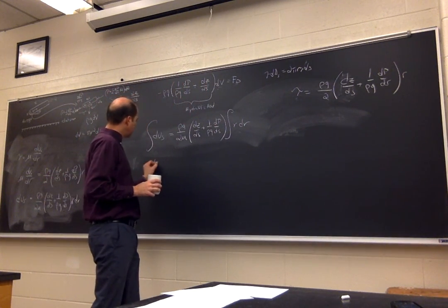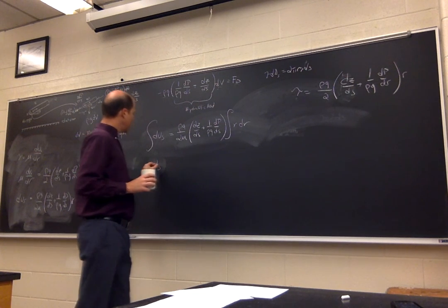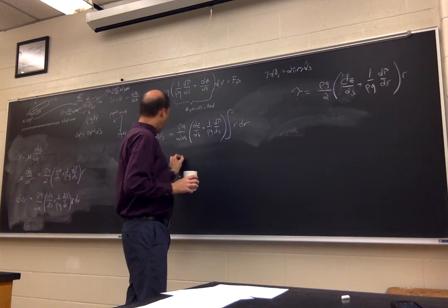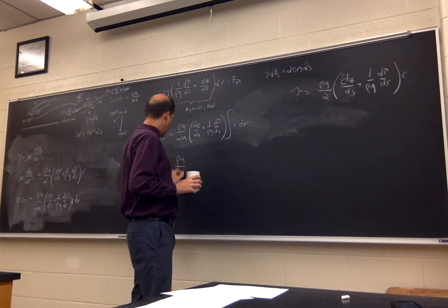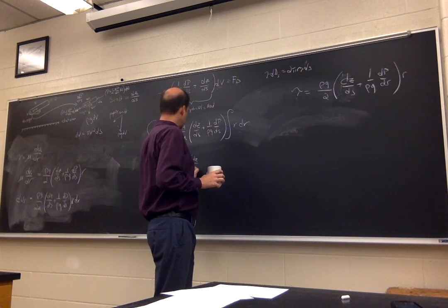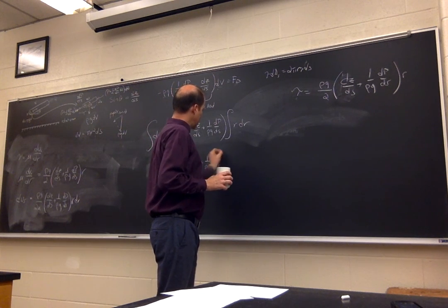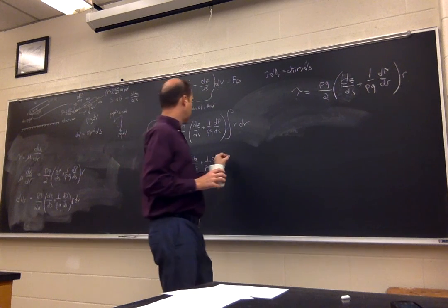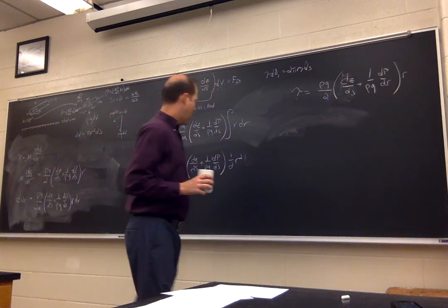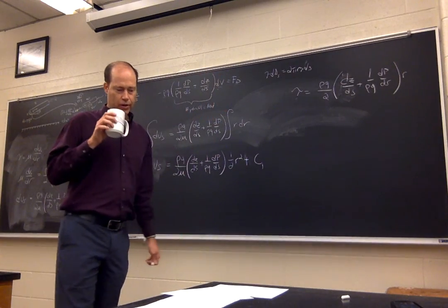On this side, we have du sub s, I have the velocity profile of u in the s direction because I've summed up all the little pieces. On the right-hand side, all the constants are exactly what they are. They're still constants, so that is rho g over 2 mu times dz ds plus 1 over rho g dp ds. And then integrating r dr becomes 1/2 r squared, and we could add a constant of integration to that result.